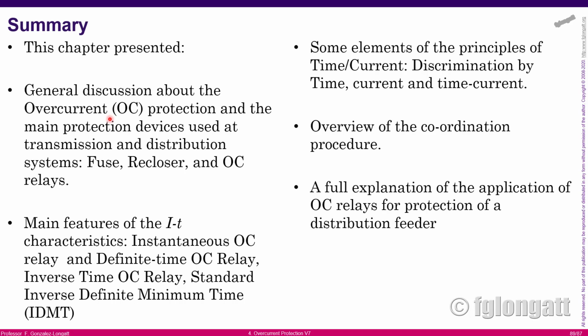Then we spoke about the main features of the current time characteristic, especially the instantaneous and the definite time overcurrent relays, but also inverse time relays, okay?